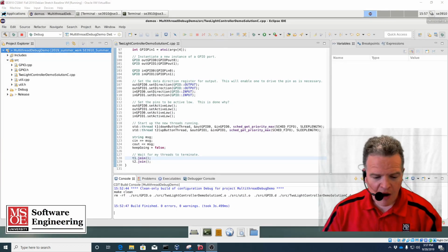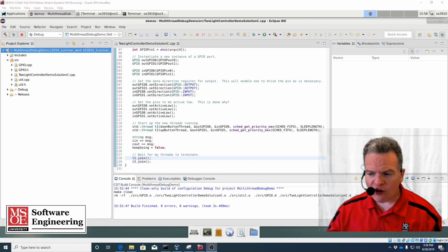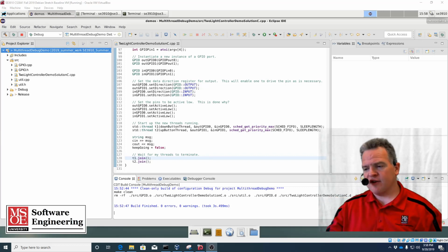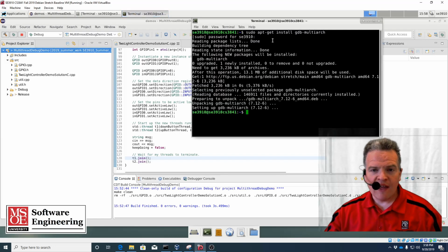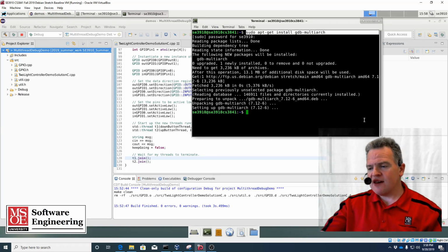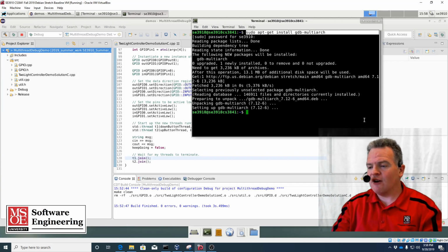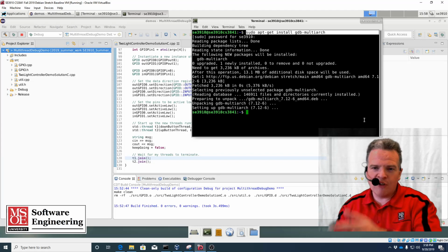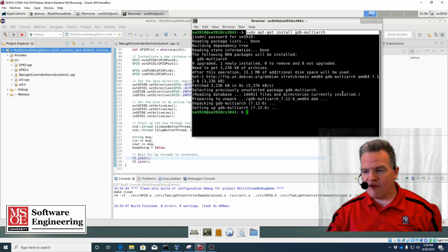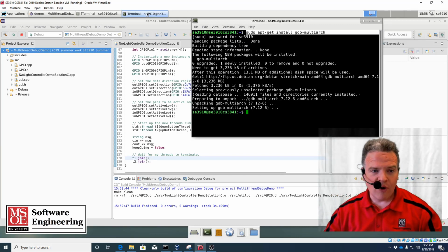So now that we have set up our Raspberry Pi device so that it has the remote debugger software installed, we need to go in and set up our host environment that we're doing a cross compilation on so that it is ready to go with cross debugging. To do that, we have a simple installation that may or may not be necessary, GDB multiarch. By definition, GDB is for the host environment, the OS that is installed on the machine, which in our case, since we're developing on a Debian kernel, basically what we need to do is install multiarch so that this architecture that we have here also supports the ARM that is coming from the Raspberry Pi. This is done once basically on the host virtual machine in our environment, and now we can actually remotely debug with Eclipse or with other tools.